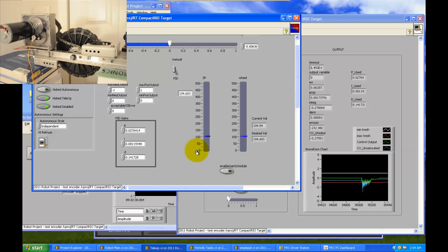And you can see automatically that was a lot quicker than where we left off before. So we have a response time that's a lot quicker. There's still a hiccup there. If you noticed when we run, there's still some jerkiness. That jerkiness is caused by the derivative, and the PID controller that we have can definitely fix that, and I'll show you how in just a little bit.